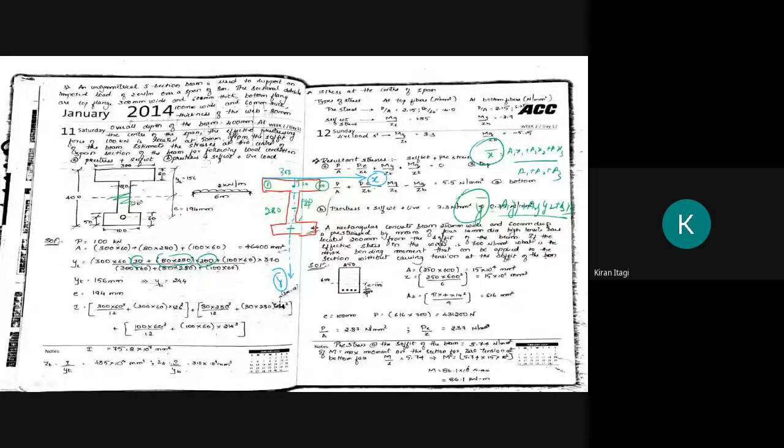So it's 140 here, 140 here, and the CG is at this point. What is the difference from here to the reference axis? That is 140 plus 60, which is 200. Therefore, this equals x2.